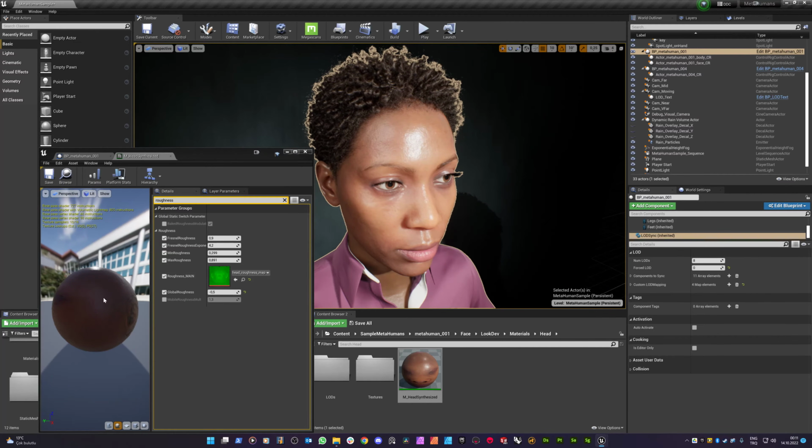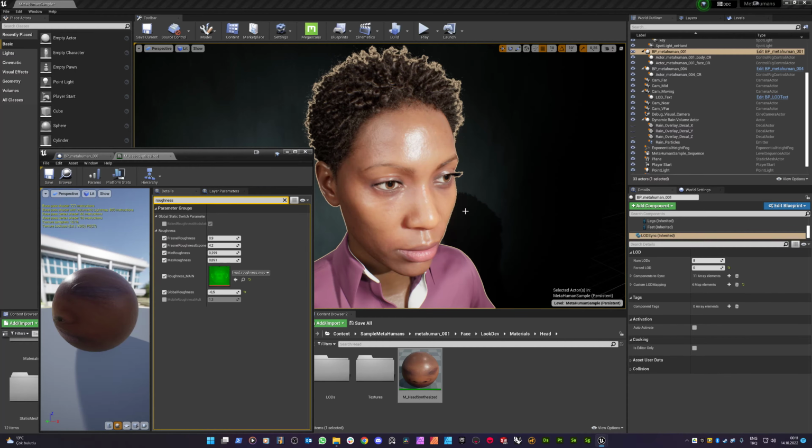So our material stays on this actor. If I set it to 1, you see that we lost the roughness value, and this means LOD1 has a different material other than this specific master material we have modified and edited.